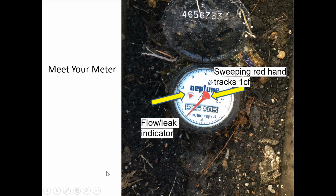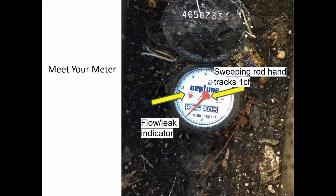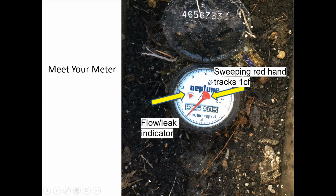So if you ever think that there's a leak going on, indoors or outdoors, check your meter when nothing should be running and see if that little triangle is spinning. Because if it is, that does indicate that there's some small amount of water that's being used. The next thing to also look at is the red sweeping hand. This red sweeping hand tracks 1 cubic foot. So 1 revolution of this meter is equal to about 7.5 gallons.